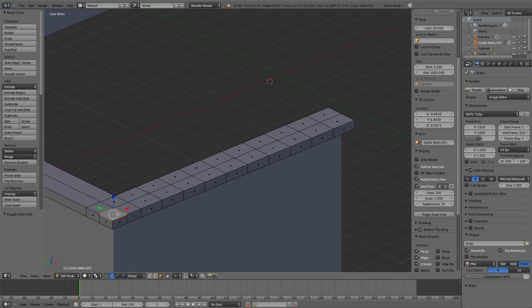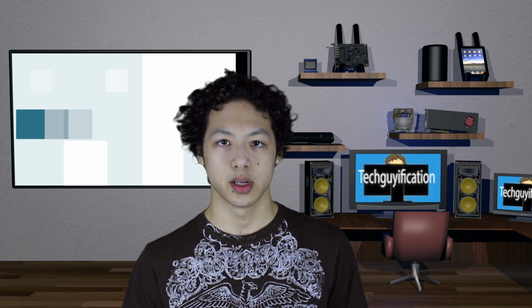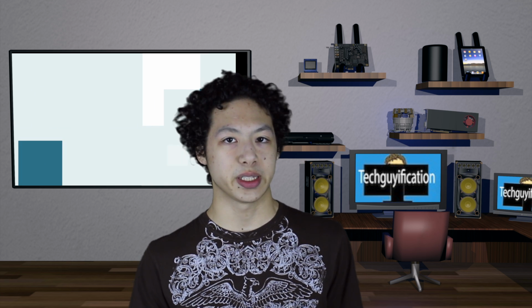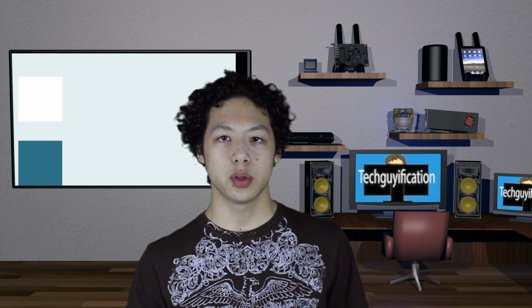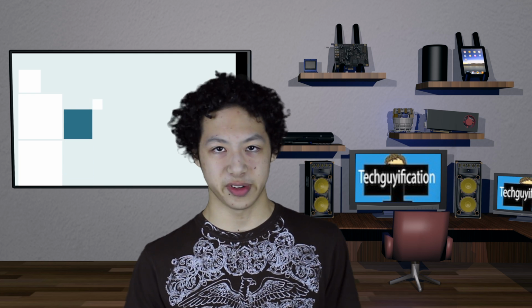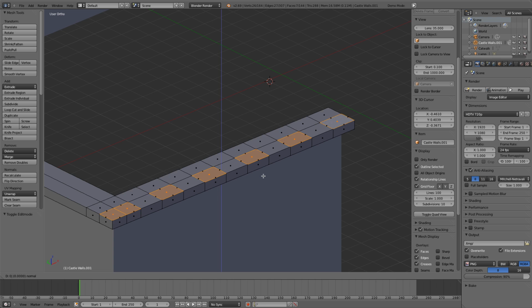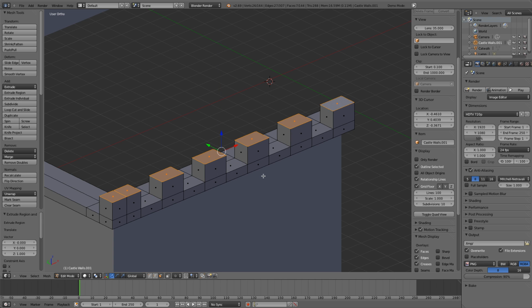So now switch to face select and then select every other face along the top of the catwalk. You may find this easier to switch into solid shading mode by pressing Z so that you don't select the bottom faces, as that can sometimes happen. With these faces selected, press E and then -1, which will form the blocks which we will use a bit later. So now let's have a look at what we've done.